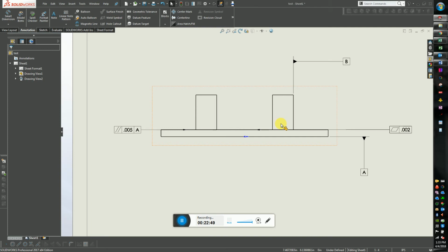So say you have a square frame, and you want an arm coming off of that frame. You're going to want to call that perpendicular, so it's not just welded on there crooked. It's easiest to measure that through a perpendicular or parallel symbol, because then you can throw a square on it and see very quickly whether it's perpendicular, flat, or parallel. Does that make sense?